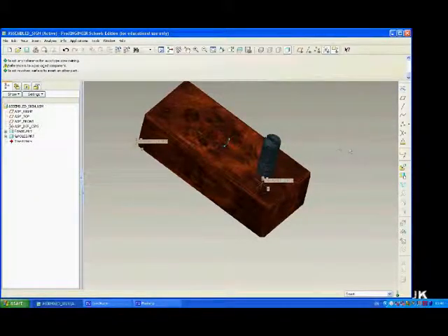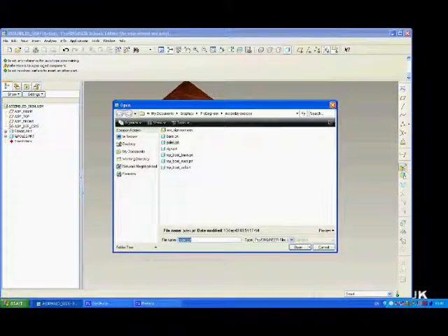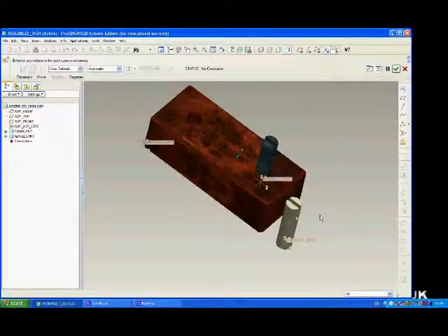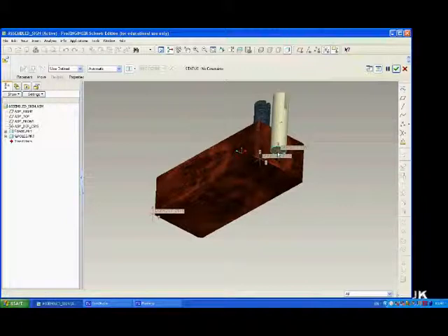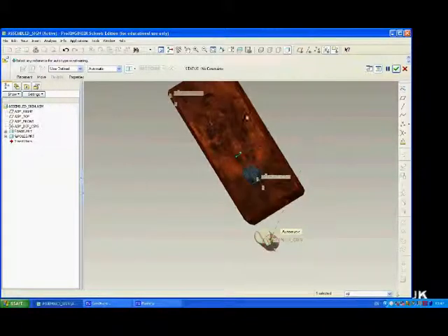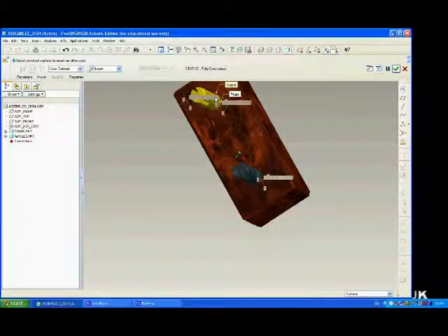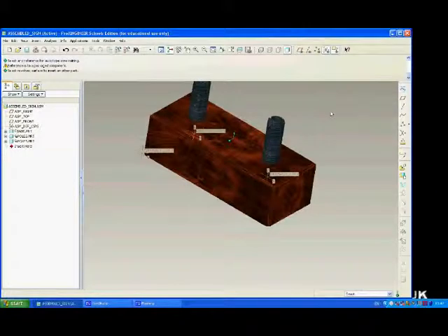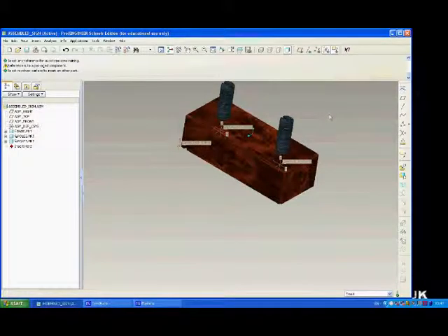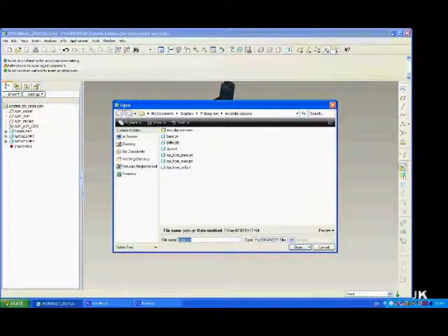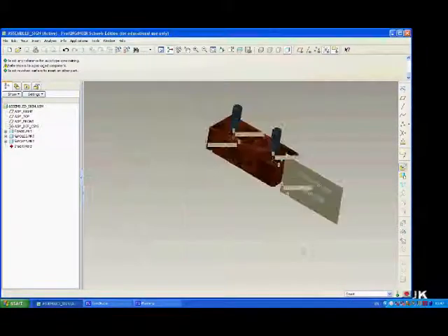So click on the add icon, pulls, open, click on the base of the pole, spin the block round so you can see the base of the hole, then select the outside of the pole and the curve of the hole. It's in exactly the right place again, so the green tick will be perfect. What we're going to do now is we're going to add the sign to this assembly. To do that, again, we're going to use this assemble icon. We're going to select the sign, then open. And you can see that we've got the sign sitting in here.